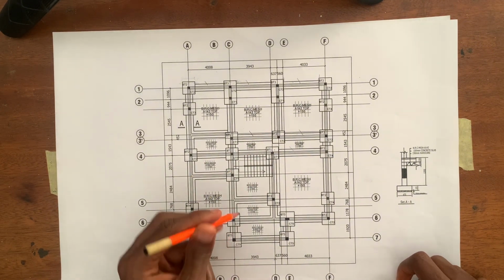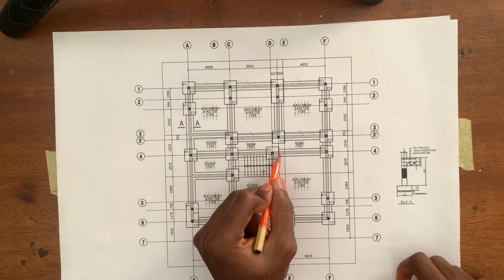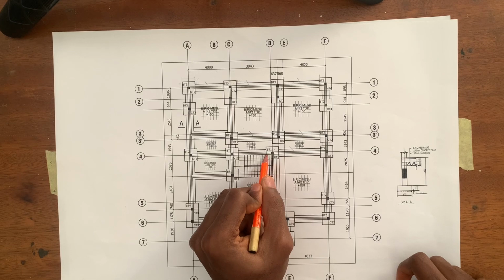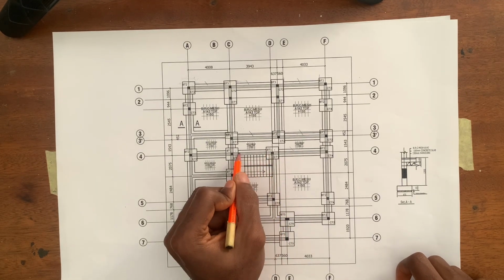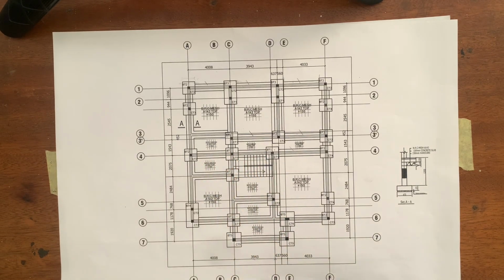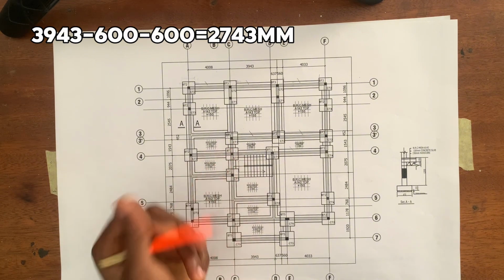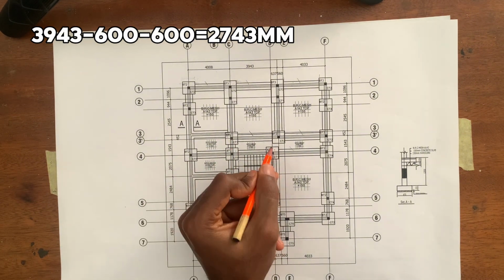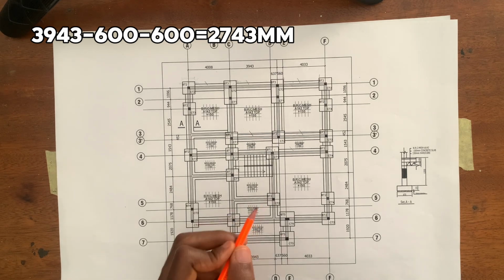3,943. So all we just need to do now is to minus half of the length of this base type 1 and half of the length of this base type 1 from 3,943, and that is going to give us the distance of this trench. So 3,943 minus this half, which is 600, minus this other half, which is 600, will give us 2,743.